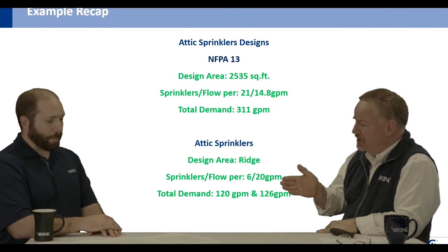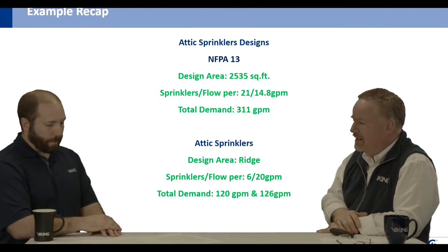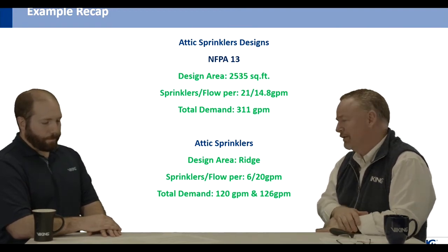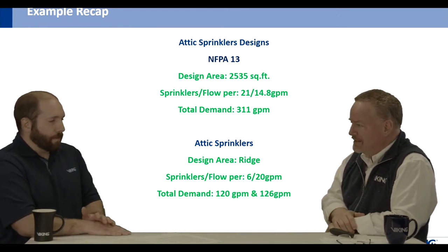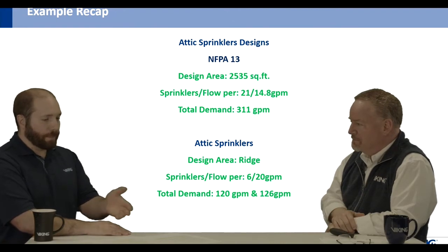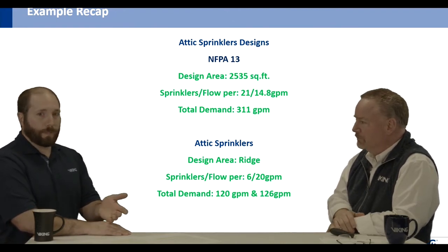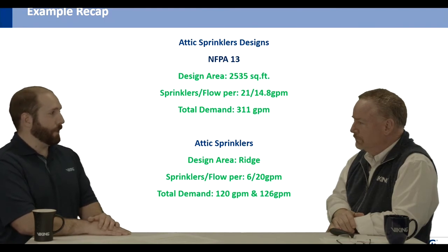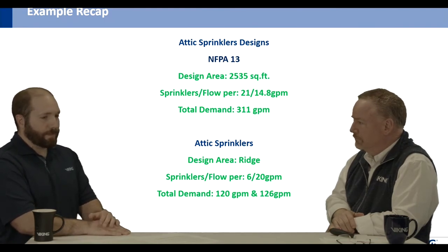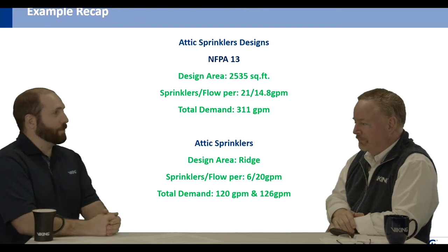Any hot questions that you usually get, common questions on the attic sprinklers that you want to go over? Yeah, absolutely. There's a couple that I get occasionally, in addition to what we've already covered. One of those questions is, can I use the attic upright sprinkler all by itself in an attic, instead of using, like you would, a standard spray sprinkler?